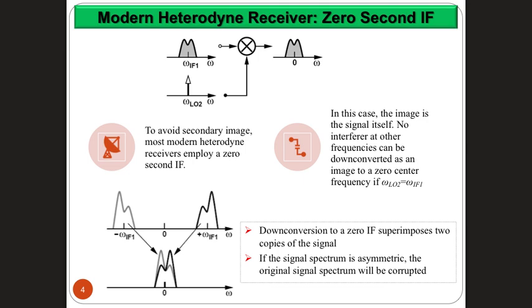So basically, in this case, first stage brings to an intermediate frequency, second stage brings you directly to 0, without the use of envelope detectors and stuff like that I mentioned at the start of the lecture, right? So now you are going to 0 frequency or the baseband signal directly by 2 mixers or multiplications or demodulators, one after the other. So one in intermediate frequency, and then the second one takes you directly to the 0 frequency. The nice thing about this is when you go directly to 0 frequency, you end up getting rid from the second image problem, right? Whenever you are not doing intermediate frequency, you don't have an image problem. However, there is something called self-image problem,